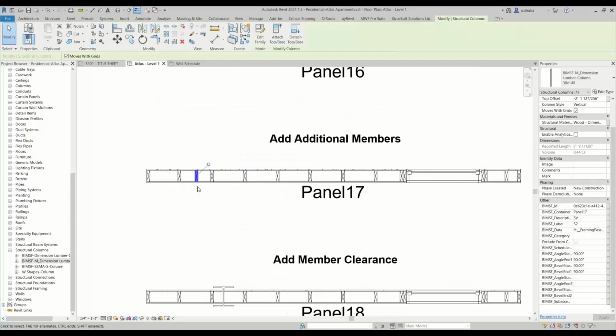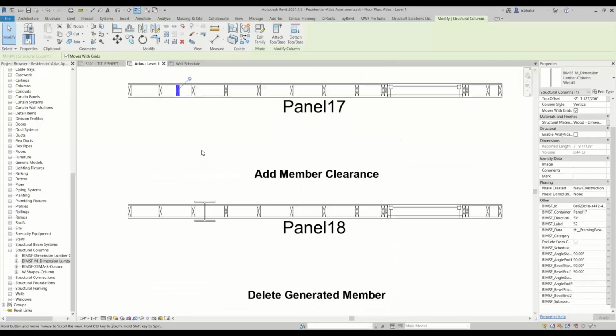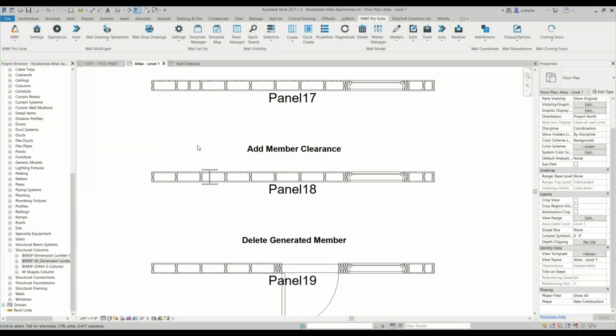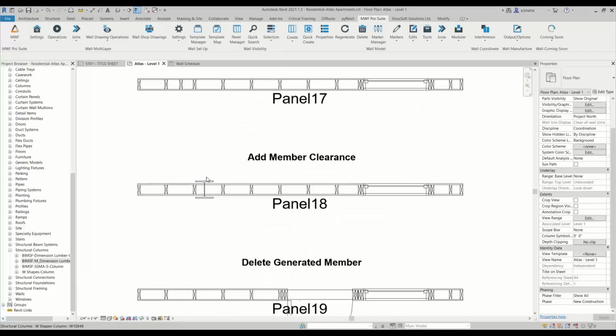And this same thing happens to both of them. They get pinned and they don't go anywhere. So if your panel does move, you actually have to remember to unpin this and move it with the panel and then repin it back, because it's not going to move with your panel because of Revit. Revit pinned elements cannot be moved, right? So that's the benefit of using add structural and add extra.